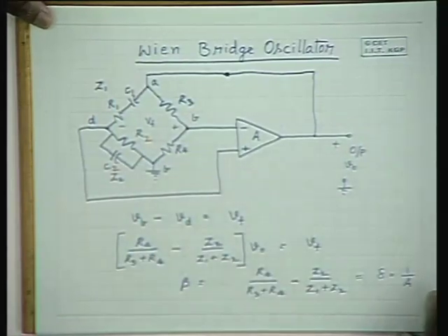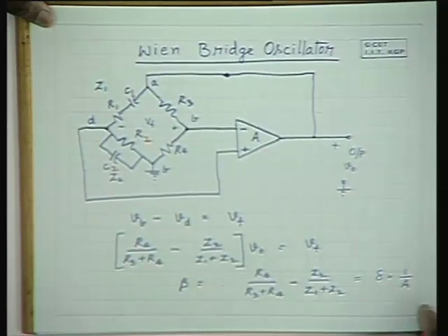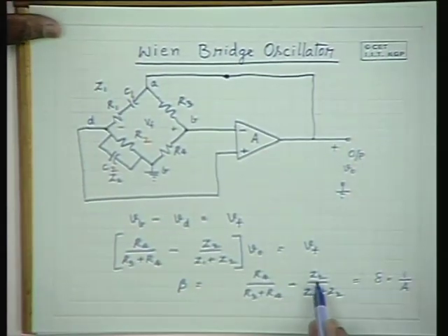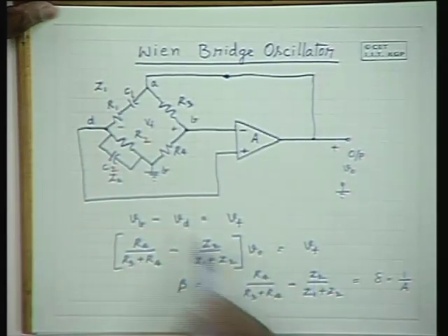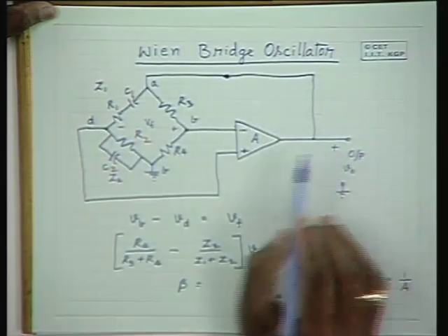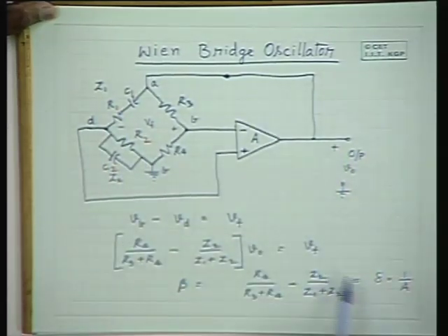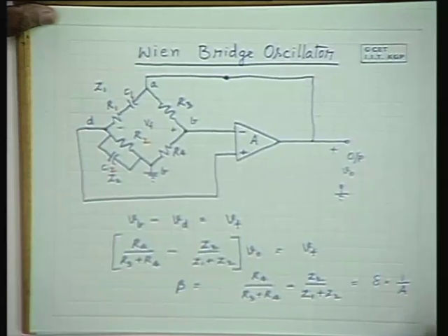So the Z we write in this equation, do we need the mod values of the Z? The Z we used in this equation, no, these are absolute values, because it is just a voltage division between Z1 and Z2 and supplied by V0. Therefore, there is no modulus here, and that is why we are getting an expression for phase shift here. In Z1 plus Z2, the imaginary terms get cancelled. That is the beauty.